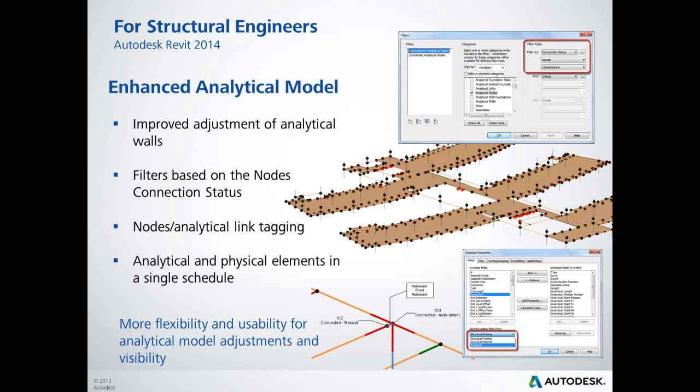This improves your ability with Revit to manipulate the analytical model to help solve round-tripping issues between Revit and structural analysis software.